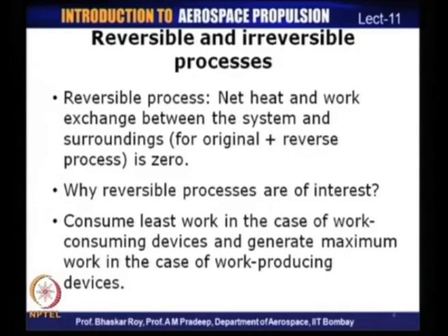Why should one be interested in a reversible process? Well, reversible processes are of significant interest because these are devices which will consume the least work if you were to consider a work requiring device like a pump or a compressor or a fan or so on. These devices require work input, and if this particular process was to be reversible, these devices will require the least work. And if you also consider those devices which generate work like a turbine, then if the turbine is undergoing a reversible process, the turbine would be generating the maximum amount of work.